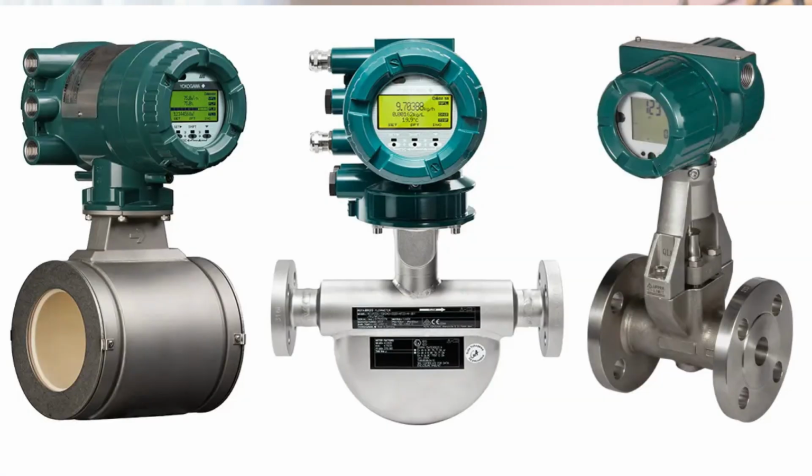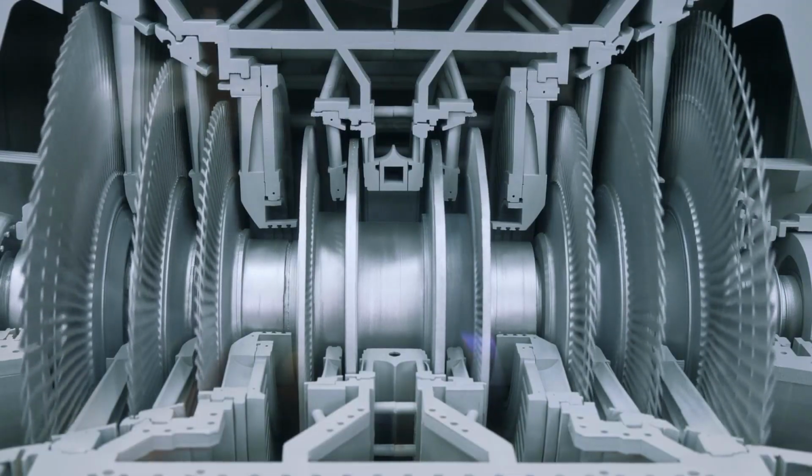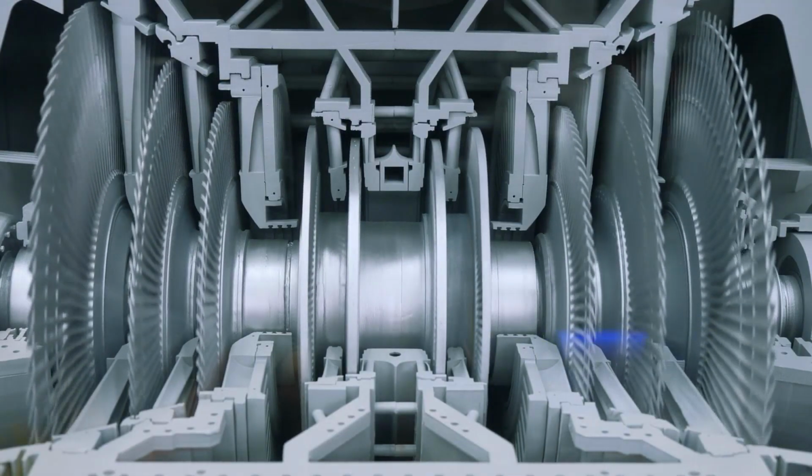For example, we'll be looking at the mass flow rate of the hydrogen, the turbine thermal efficiency, the turbine power output, and we might also look at the flue gas composition to make sure that we can understand and see how the machine responds to these changes that we're putting in with the hydrogen.